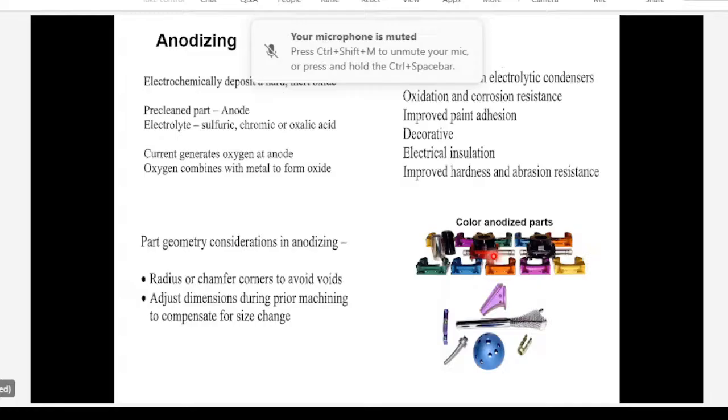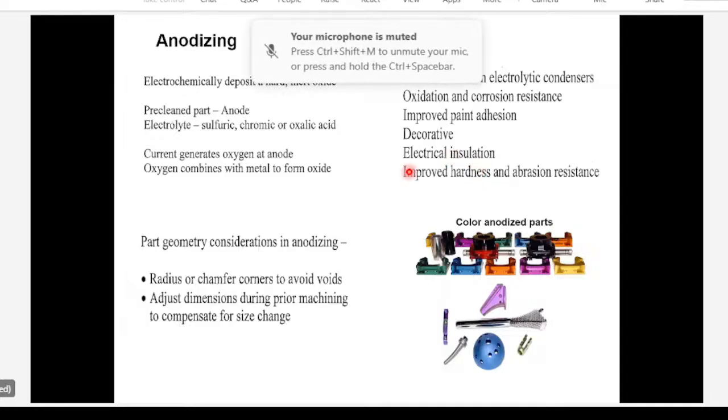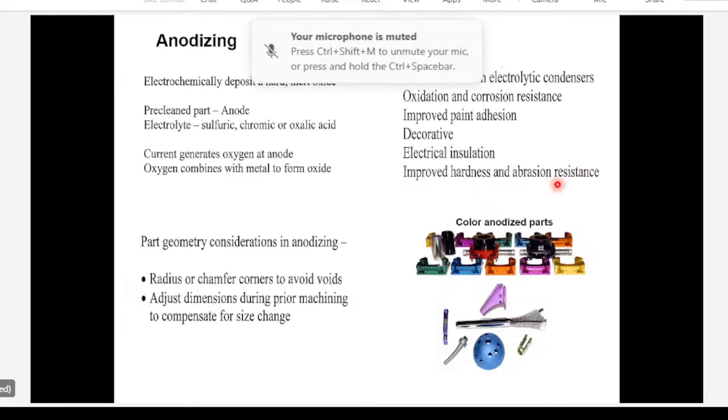Anodized coatings are always very porous at the nanometer scale, so those pores can be impregnated. Because oxides are electrical insulators, anodizing creates an electrically insulating surface. And oxides are very hard materials, so wear and abrasion resistance also improves.